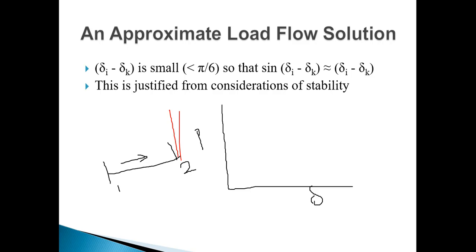What happens is that as you slowly increase the delta, the power flow increases, but then the power drops. So delta can be at max 90 degrees. But we do not go to 90 degrees because any more change in the delta, the power will drop and the delta will start increasing. So this system will go unstable. So we keep the delta within a range less than 90 degrees and do not go towards this zone closer to 90 degrees.